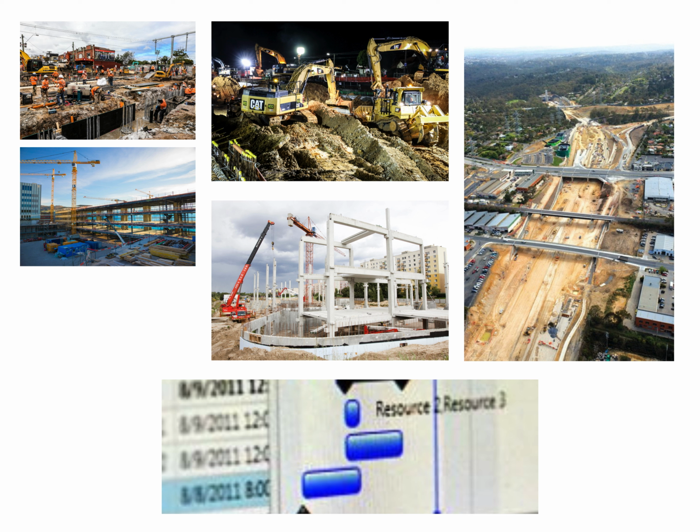Understandably, more complex schedules would take considerable time in calculating the critical path using manual calculations. Our assumption of every day being a workday has also simplified the calculations. Likewise, our assumption of an 8-hour typical workday. CPM software makes this fast and more accurate. However, the basic fundamentals of CPM need to be clearly understood to understand what CPM software is telling us.